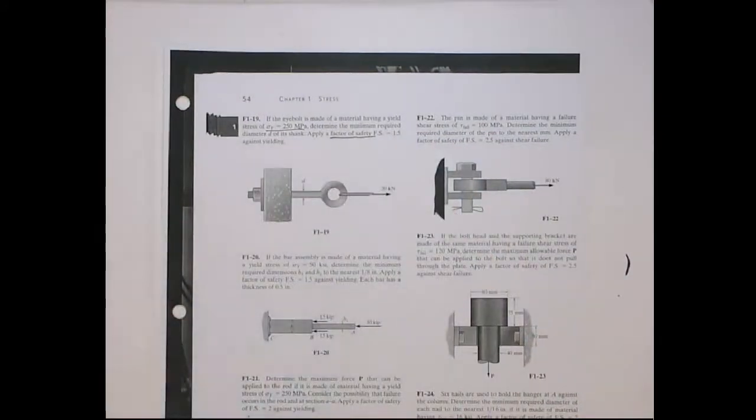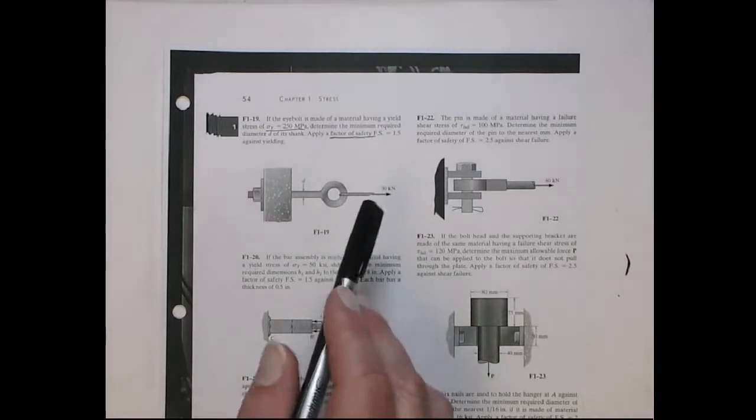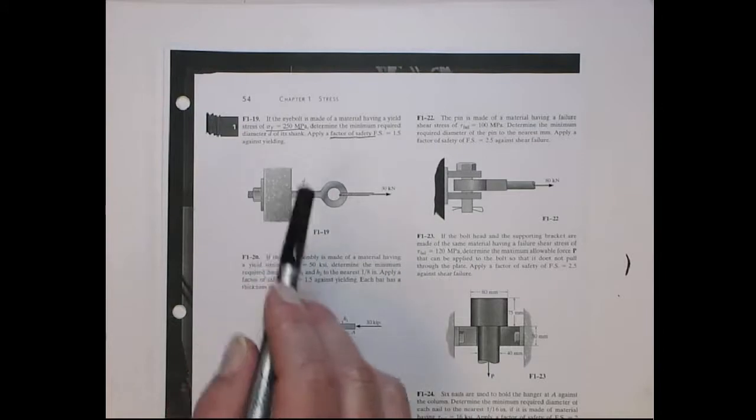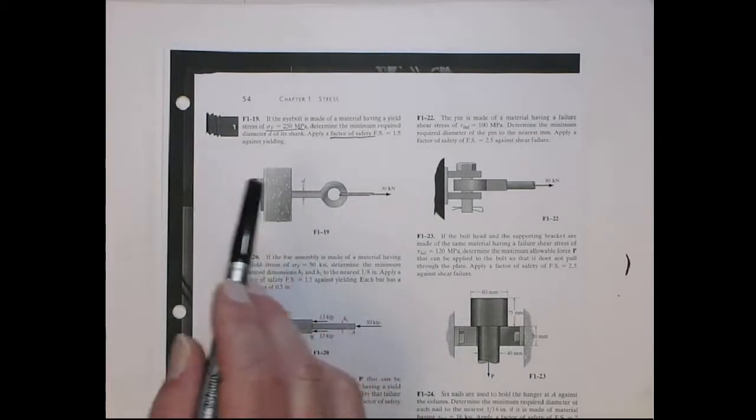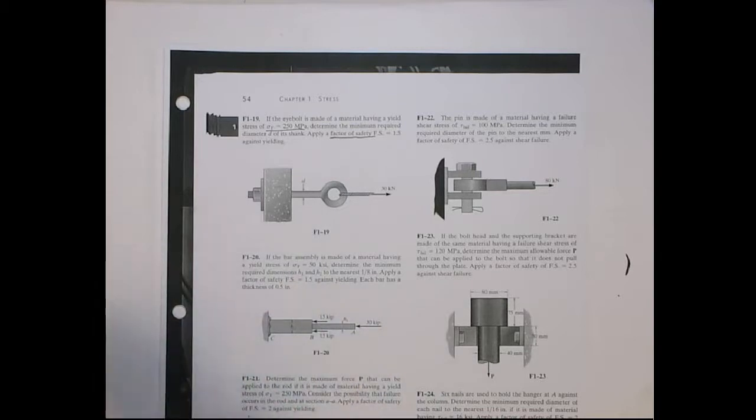Typically, in reality, you don't know fully these boundary conditions. There might be some dynamics. There might be some other misalignments or geometrical errors that might happen. You're designing sort of the ideal situation, and so they want an additional 50% factor of safety here.